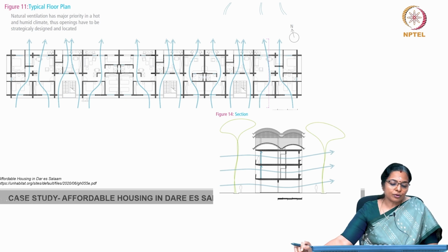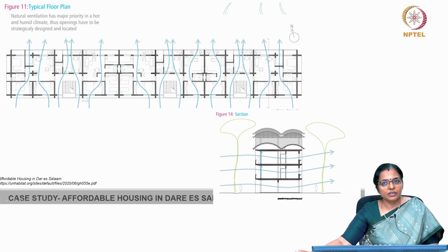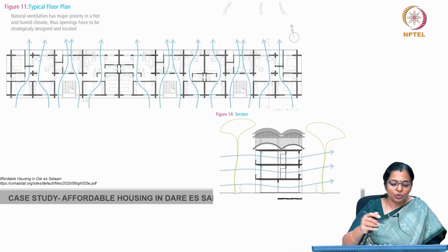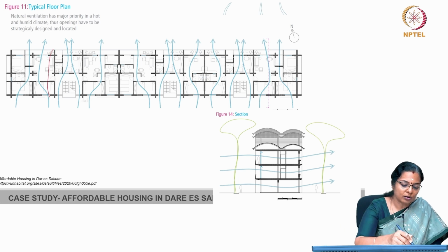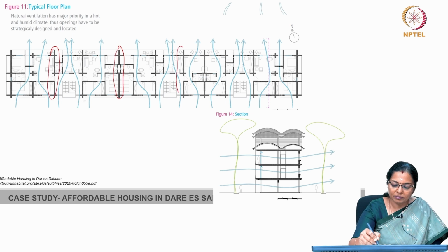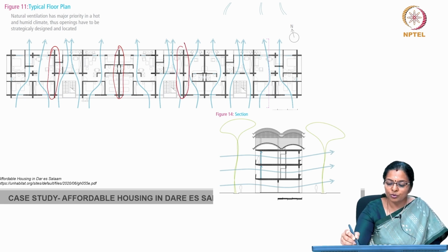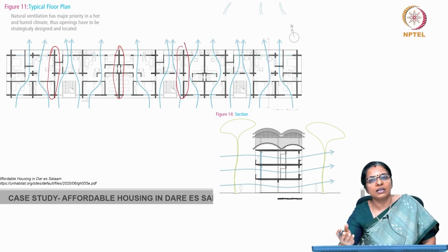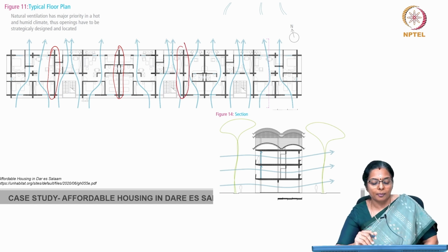So, most of the houses that you saw in the first picture, the primary facades of these apartment blocks are strategically oriented along the north and south. So, you can see for most of the house, the western side is completely insulated. So, you do not get the western sun inside the house.